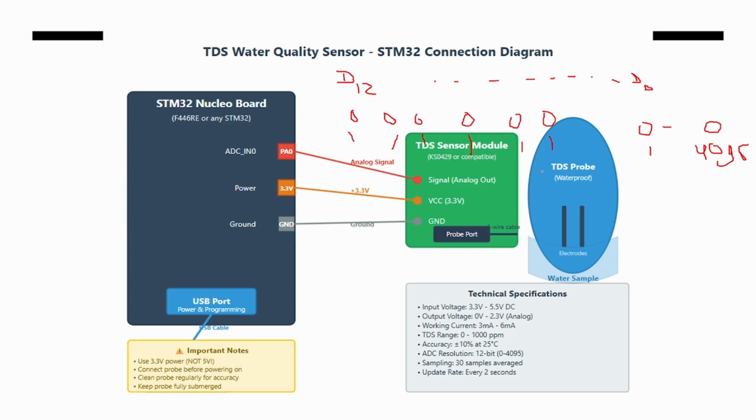So if you have a 12-bit ADC, for each input value it will generate 12 binary output digits, and then you can convert this binary into decimal, and you will have some number. So whenever we read this ADC, it will give us this type of number: 256, 1024, 325, right? And we have to convert that number into voltage.